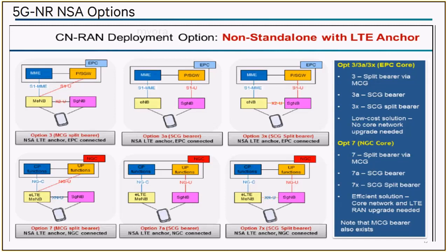So at least from a requirement point of view, there are already requirements which state that you are transmitting on LTE, you are transmitting on NR, and this is the max power you are using on NR, and this is the max power you are using on LTE. So there are requirements already in place, which means release 15 of the spec allows for an uplink CA sort of thing between LTE and NR as well. What is the use case? I don't see a use case, but you know.